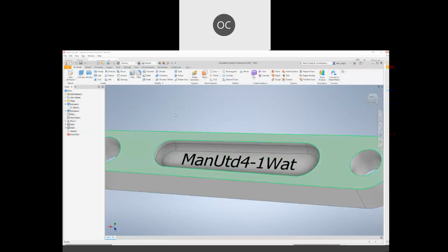I would like you to try on create here. You have what we call the emboss features. So click on emboss. So profile will refer to the text that you have just created. That will be the profile. So at here, you can select the depth itself.